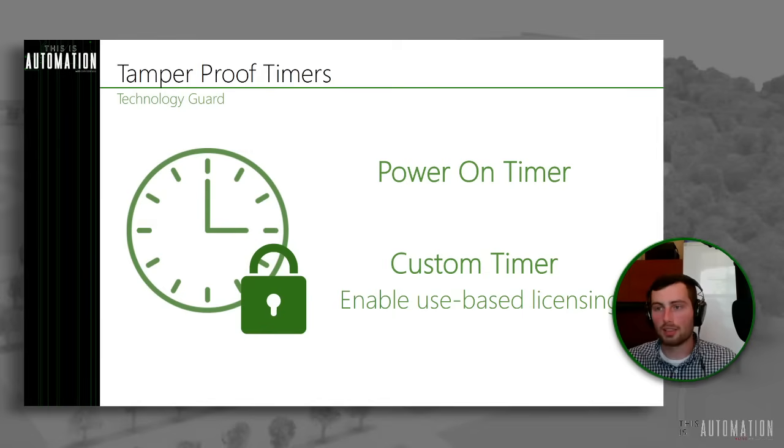Again, if you're using just a standard variable or tag to count time for something, that can be overwritten just as easily as you're writing to it. Certainly if you're writing to a standard USB into maybe a text file or a CSV file to log some time of usage, the end customer could feasibly take the USB out of the system, plug it into their computer, make a change, and then plug it back in. Again, we hope that's never the case, that there's any maliciousness, but it does happen, right? So we have to put these protections in place because this stuff inevitably does happen.